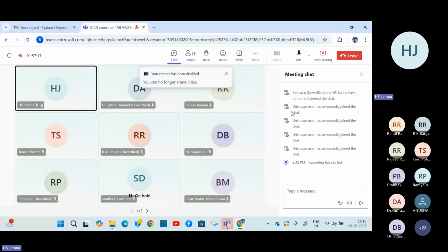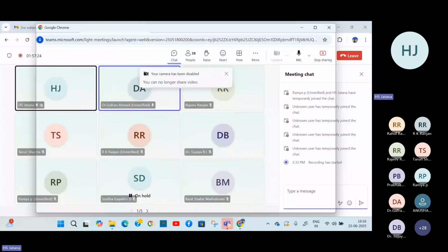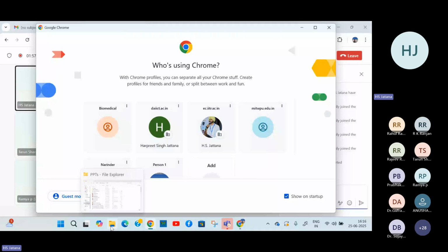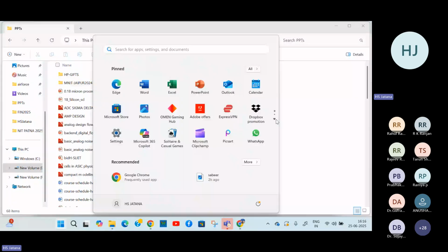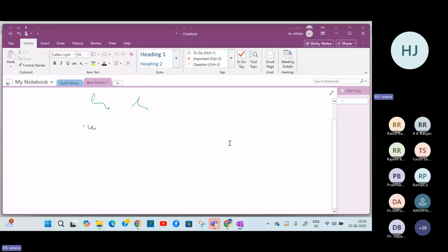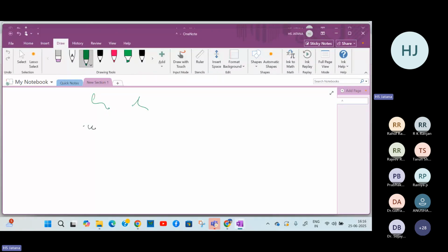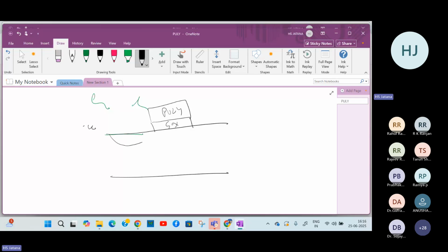Yeah, the basic reason is the design of the transistor is different, right? Because of the design, that is the process engineers will design the transistors, and the differences in the transistor are very minute. It's not very huge differences. I will tell you. You see the transistor, whatever transistor we have studied, we have a gate oxide, and then we have a poly here, and then we have a source drain like this, and then we have an isolation here.